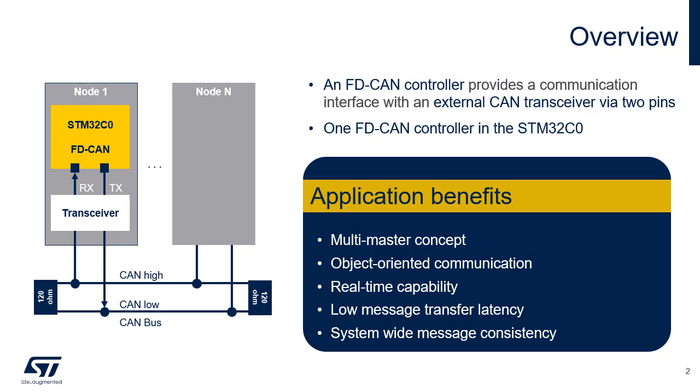A multi-master concept with message prioritization. Object-oriented communication, which uses content identification instead of node addressing. Real-time capability with low message transfer latency. System-wide message consistency, with built-in error detection and management mechanisms.